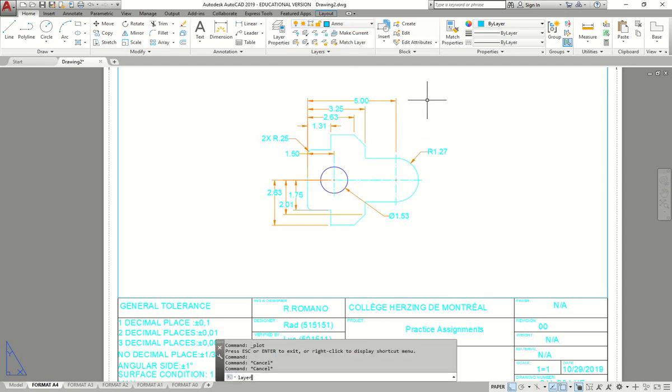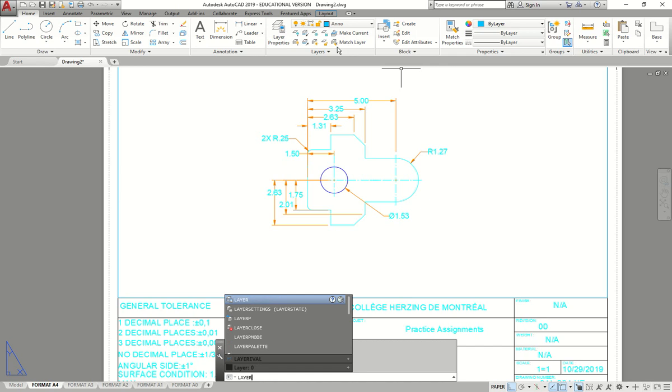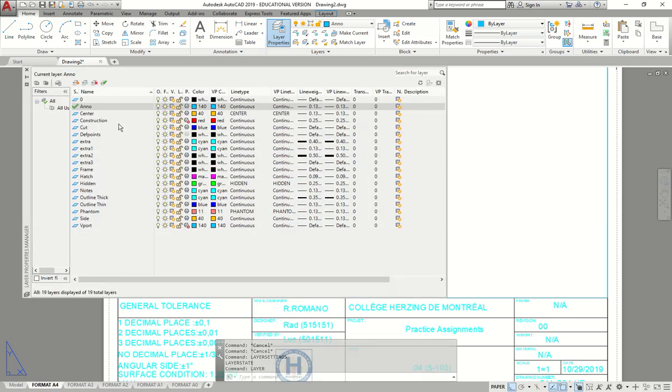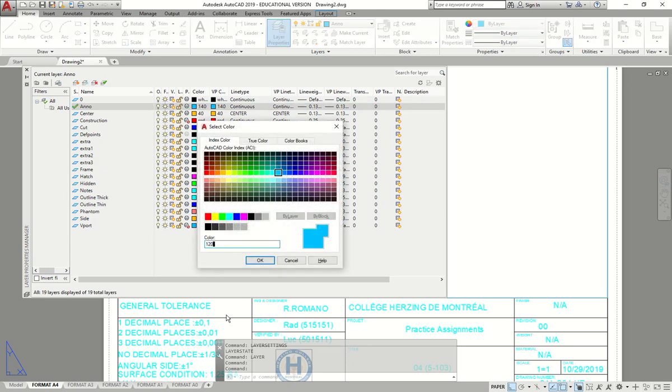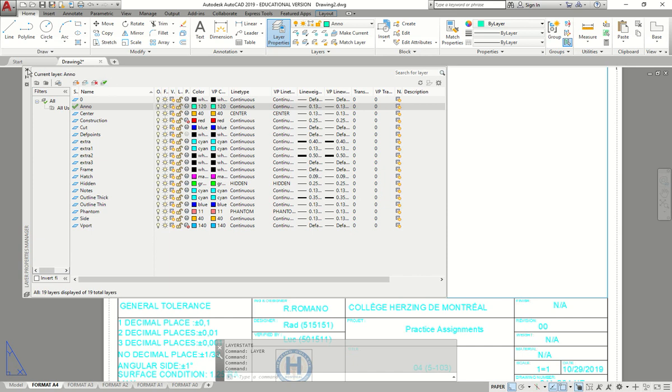Again, if I go to layers, you see here that if I look at construction, it has a little symbol saying do not print. You have it on this one and also the defpoints. If I want my dimensions not to print, for example, I will go to Annotation and put do not print. And right now when you go print, none of the dimensions will show up. But we don't want that, so let's change it back. That's good. Let's make our dimensions a little bit lighter. Put it at 120. Close it back. And let's go print.